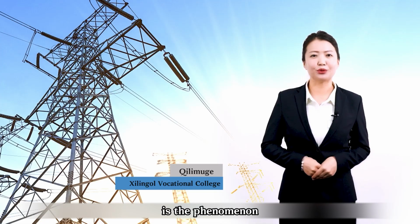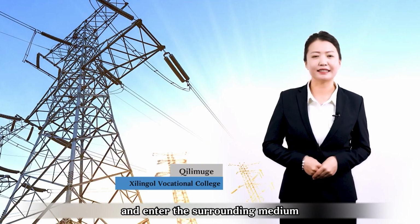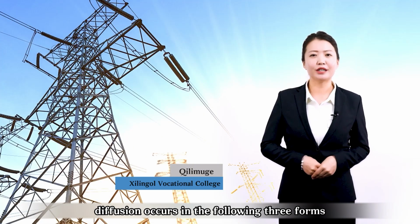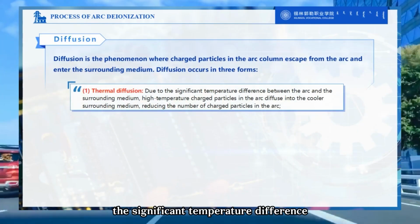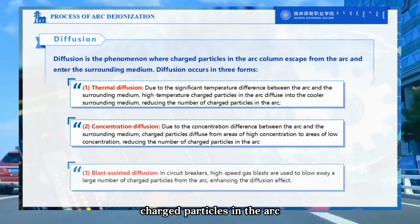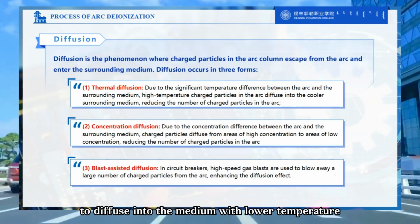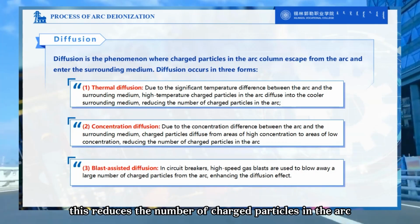Diffusion is the phenomenon where charged particles in the arc column escape from it and enter the surrounding medium. Diffusion occurs in the following three forms. First, thermal diffusion, due to the significant temperature difference between the electric arc and the surrounding medium, causing the high-temperature charged particles in the arc to diffuse into the medium with lower temperature. This reduces the number of charged particles in the arc.